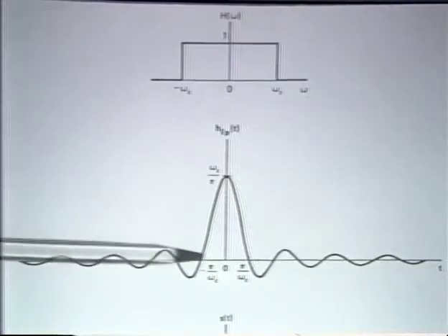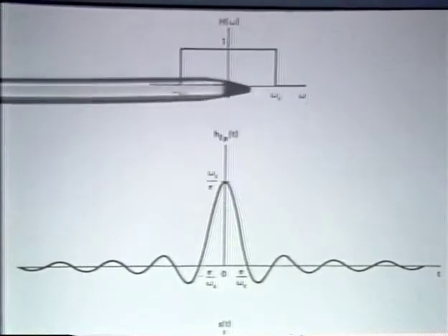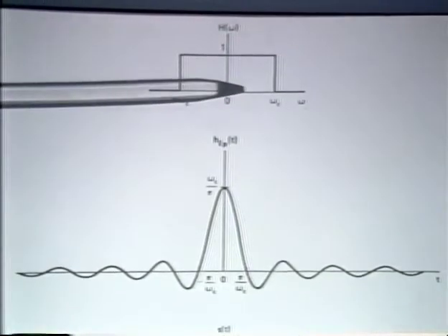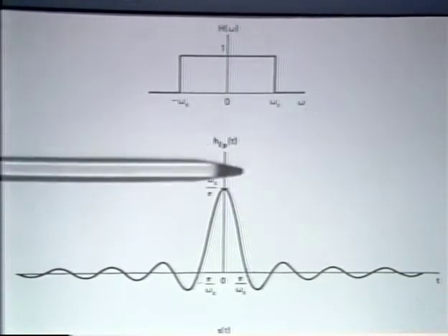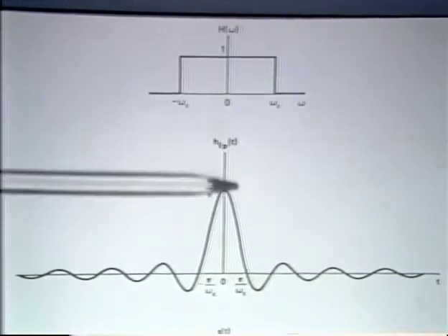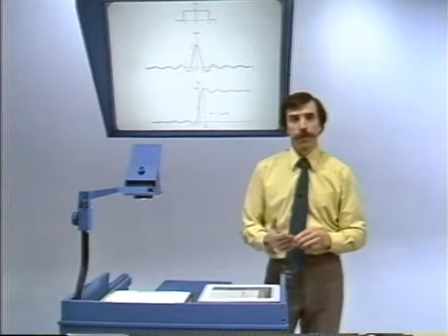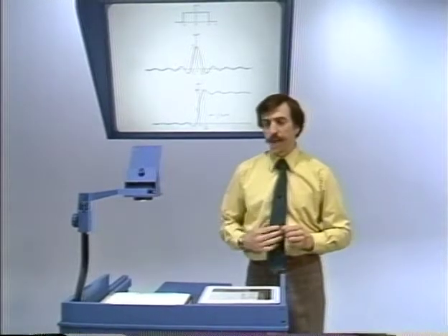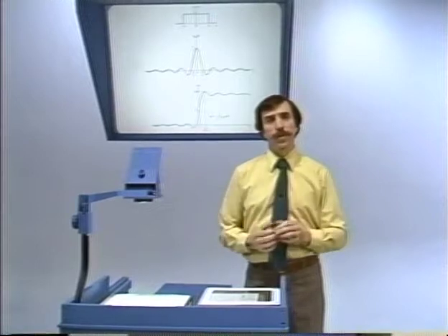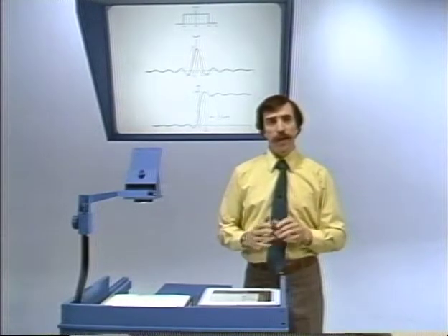And recall also that since this frequency response is real valued, the impulse response, in other words, the inverse transform, is an even function of time. And notice also, since I want to refer back to this, that the impulse response of an ideal low-pass filter, in fact, is non-causal.